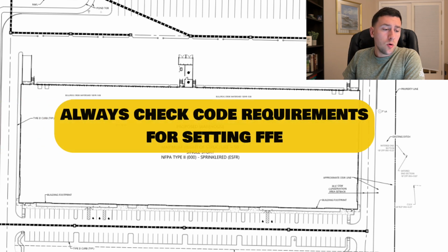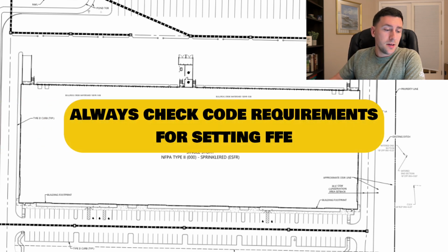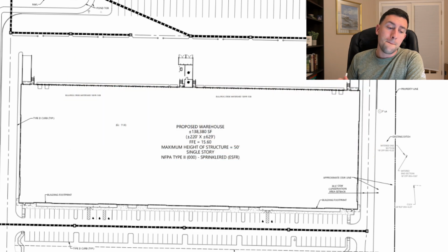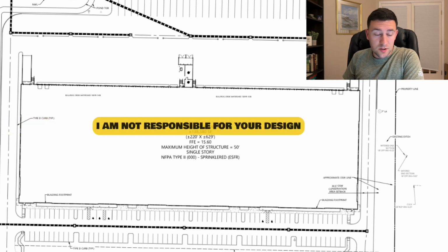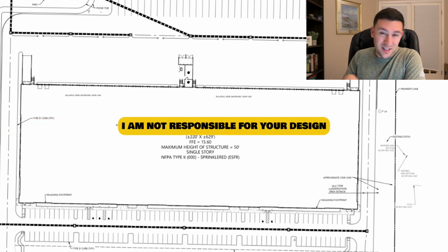Always check your code and the regulations. Typically, your building FFE has to be anywhere between 1 to 2 feet above that elevation. But again, just consult your code. I'm not responsible for your design. This is all a fictitious property.